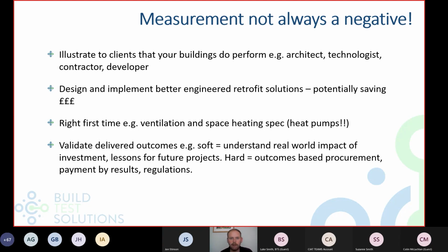When you're installing a heat pump, it's incredibly important to its efficiency that it's sized properly for the building. If it's undersized, then you won't have enough heat, which is a problem. If it's oversized, then it won't be running at its maximum efficiency, and the coefficient of performance will be worse, and it will cost more to run the building even though you can get enough heat. So it's not the same as with a gas boiler, where there's not as much penalty for having an oversized system.